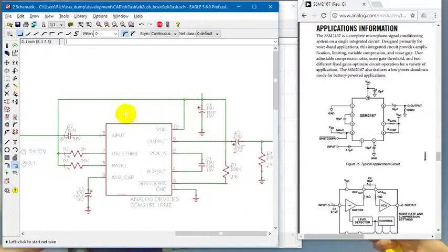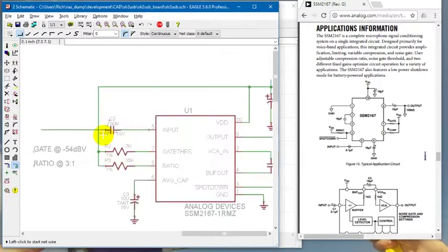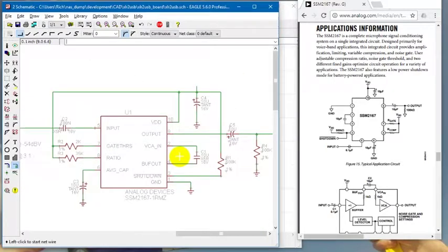But I haven't called them VDD, and I could name them that, right? If I want to, I can make it now. You also notice that it automatically makes a dot on things that are connected, and it skips the dot on things that are not. So these two cross each other, but they don't get connected. Some people say that's bad form to ever have them cross, but work with a complicated circuit, and you'll realize it's just plain unavoidable. I can also do the wire bend thing to kind of clean up R1 over here.